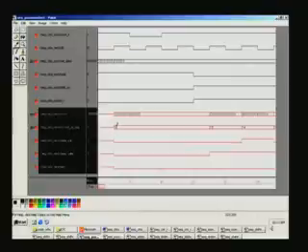Now, you need to send 16 bits, so it is initialized to 16 here, and every bit going out, this will be decremented, as you can see, going to 15 here, 14 here. Why a long gap is, we have first loaded this value by activating this high, and it goes low only here, and then simultaneously we will make the shift control high, so that with the arrival of the next positive edge of the clock, it starts and the counter starts decrementing, as well as it has output the value.